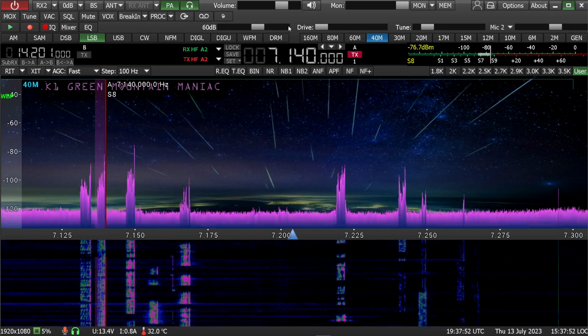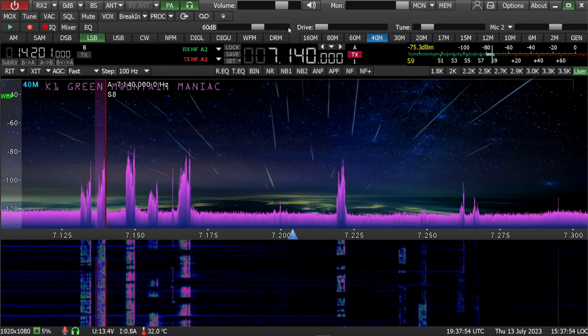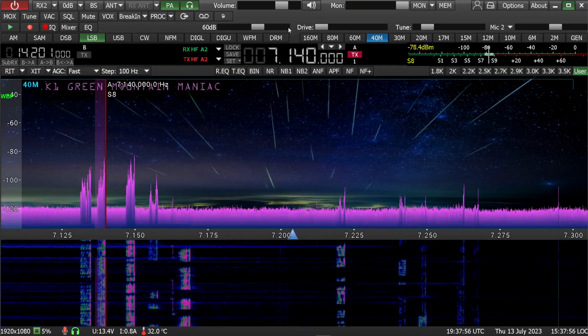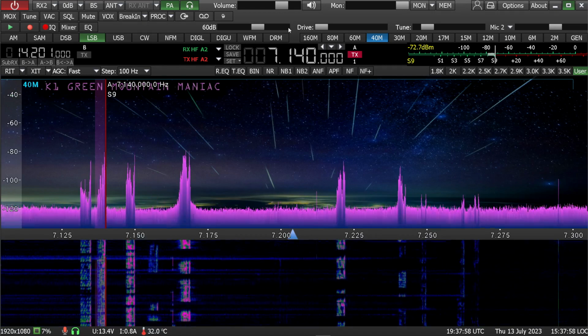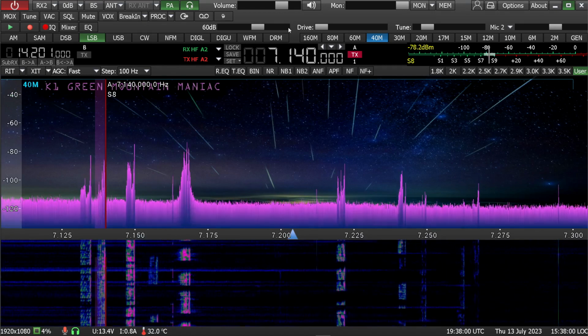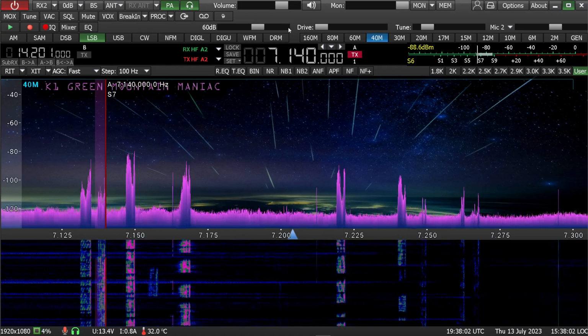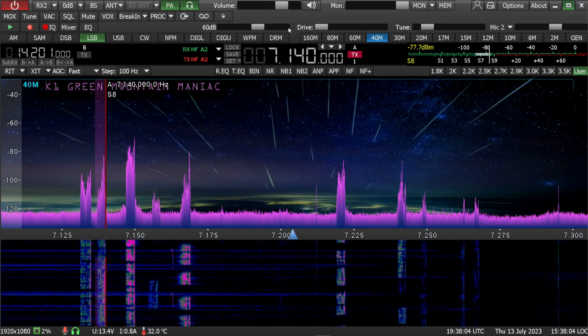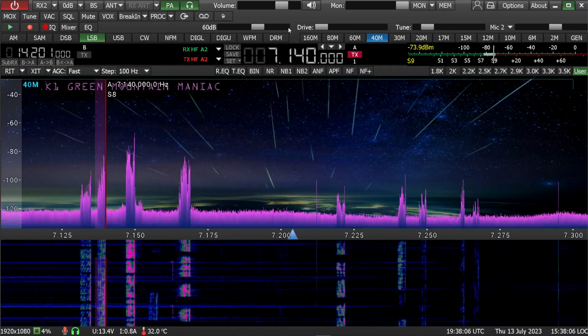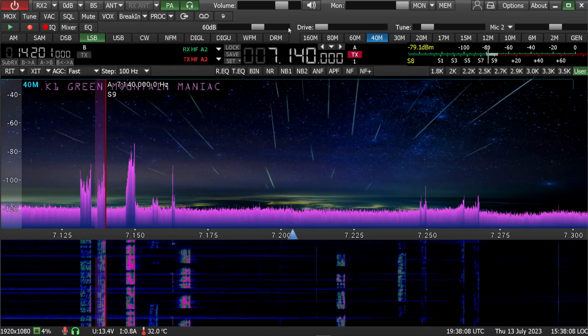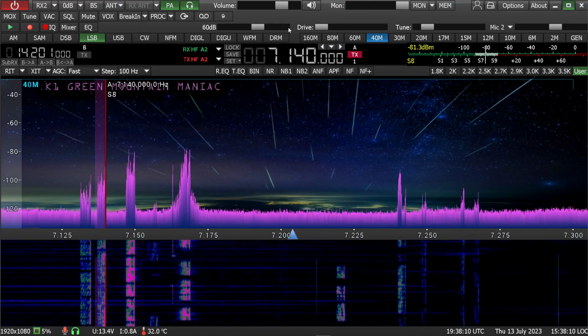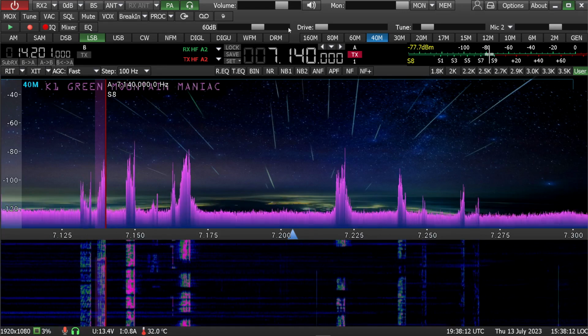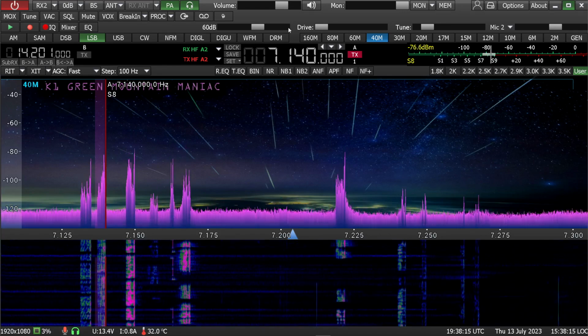When you set this up on an ICOM or any other conventional transceiver where you're using a USB audio codec, you can use a combination of the RF gain, noise reduction on the rig, mostly the RF gain at that point, and you're going to need to set the gain level on your USB audio codec. Don't set it too hot. You don't need a lot to make this system work, right?